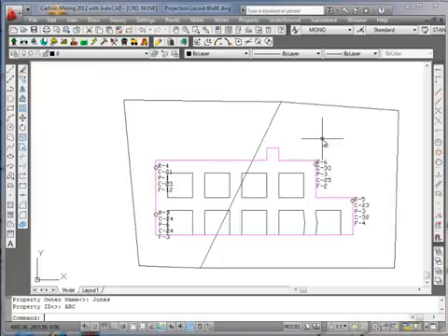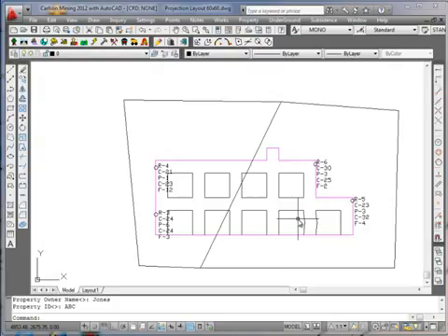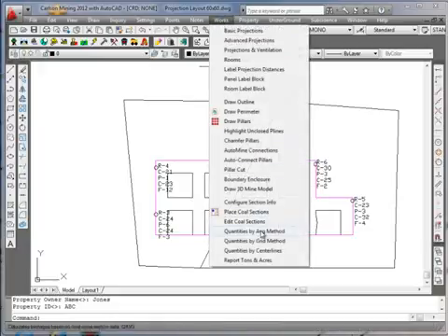So now that we have the offsets that have defined the pillars and the outside of the mining area, and we've located and taken thickness measurements for the coal sections and placed property boundaries, we're ready to calculate the tons that were mined in this area. In order to do that, we'll go to Works, we'll go to Quantities by Average.